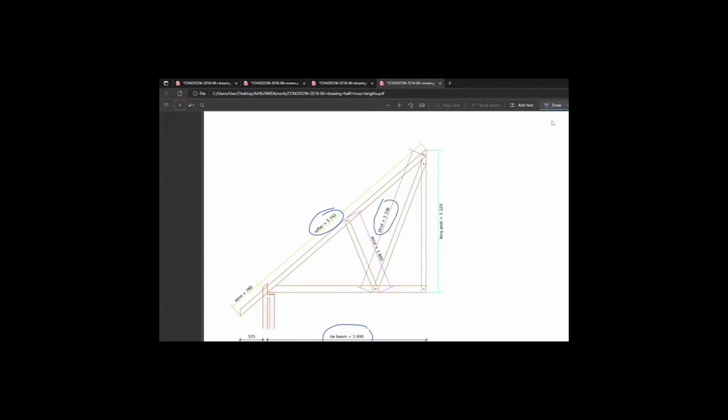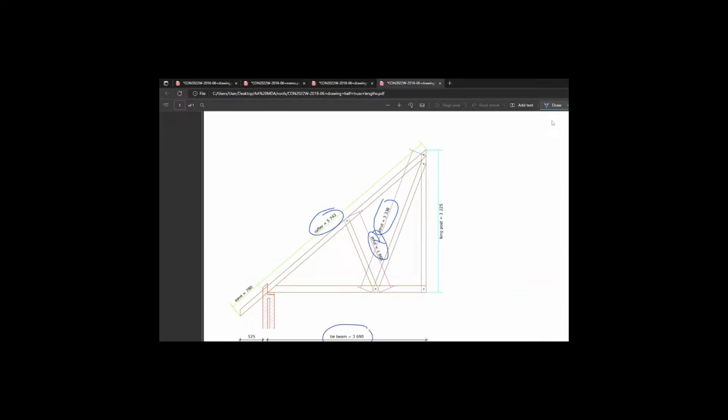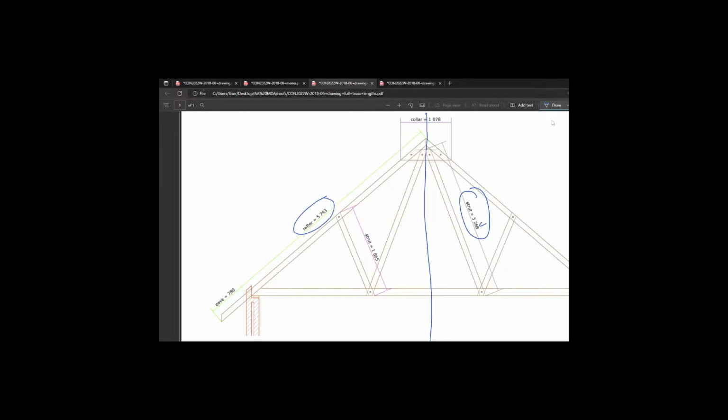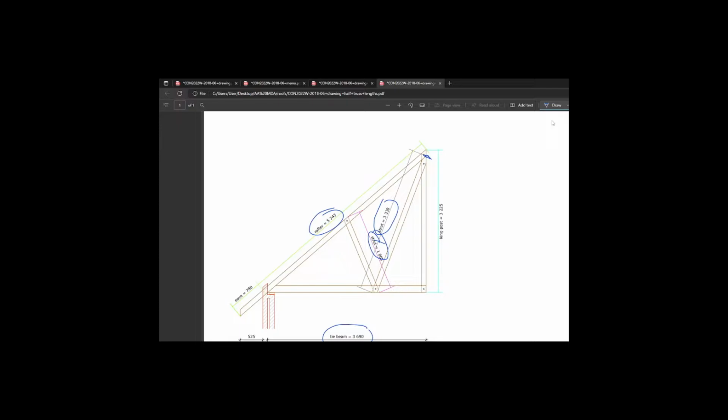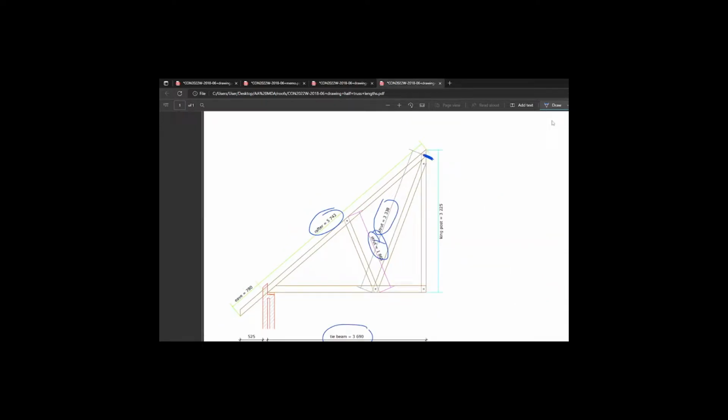What has happened here? Let's just take a look. 1.865, 3.338, 3. That's interesting. The longer strut, slightly different, guys. See that? 3.338, 3.268. Okay, interesting. But the shorter strut is the same. Okay, so let's not use the full truss. And I think we could. What's happened is that it's gone a bit. 3.338, 3.268. It's gone a bit further at the top. I think must be at the top, right? So this point at the top where it was scaled is a bit longer than the full truss point where it gets scaled. Tiny bit, anyway.